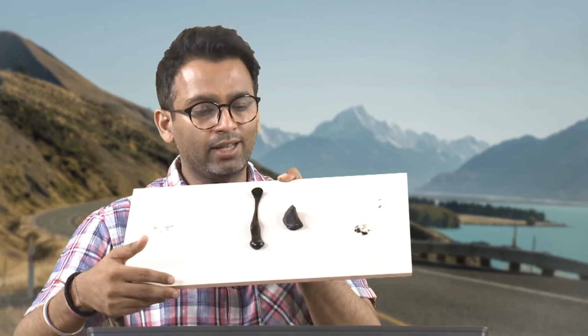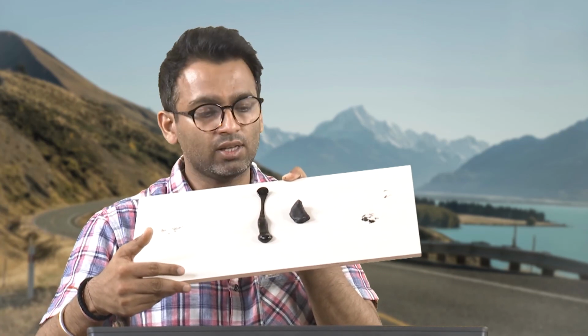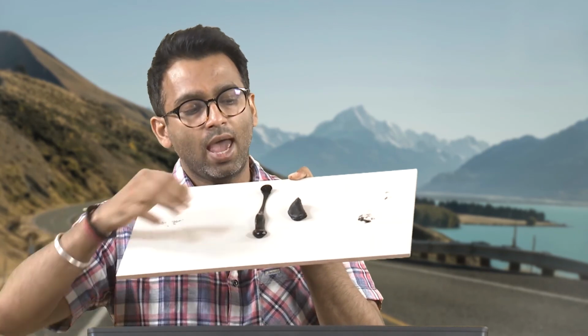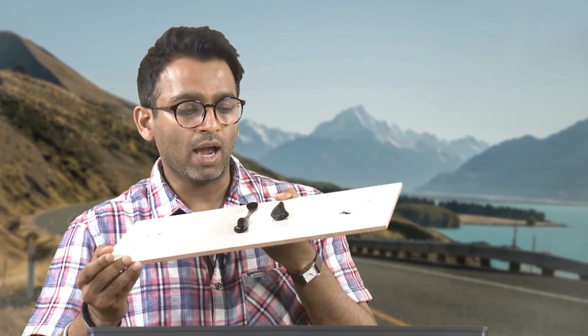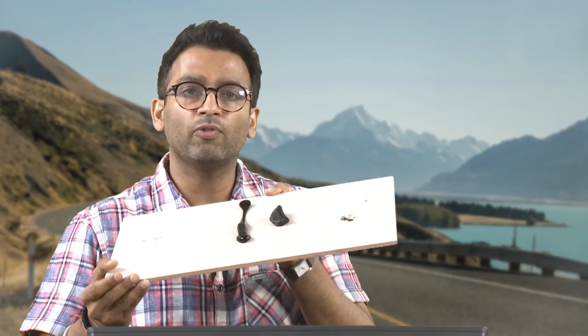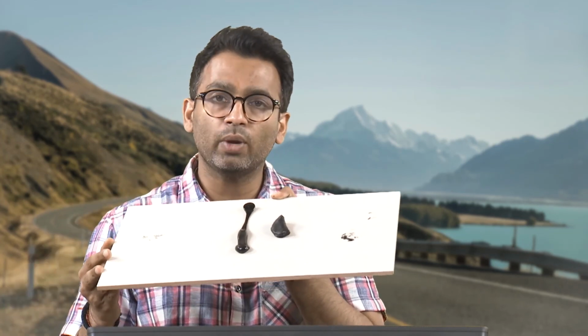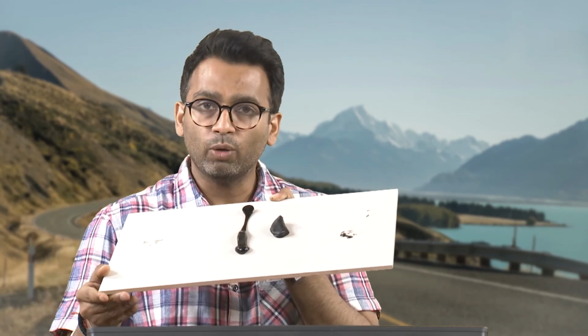I anticipate that the temperature of this room is around 25-26 degrees Celsius now, and you can see that the stretched polymer modified bitumen sample has recovered almost, I think, more than 90% here, if I remember correctly, the shape from where we started. So, this tells us how polymer modified bitumen has better recovery or better resistance to deformation or improved response to deformation in comparison to the unmodified or conventional bitumen.